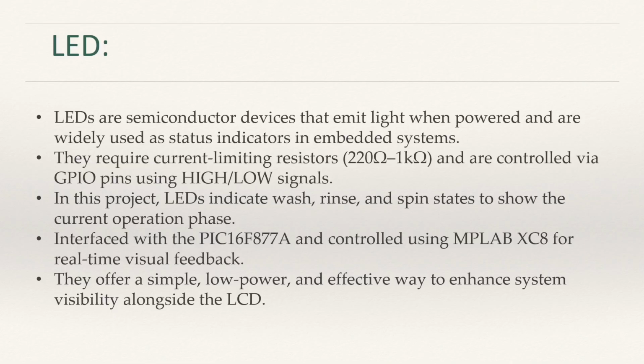LED. LEDs are semiconductor devices that emit light when powered and are widely used as status indicators in embedded systems. They require current limiting resistors of 220 ohms to 1 kilo ohm and are controlled via GPIO pins using high or low signals.